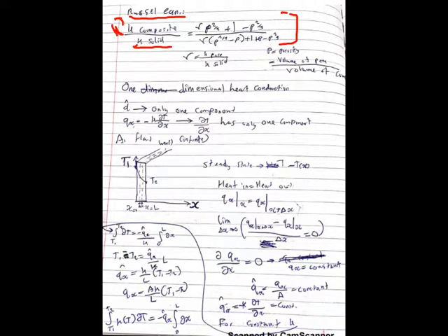We have this squiggly, which I don't know what to call it, and that is basically a ratio of the thermal conductivity of the pore, i.e., what is the pore? That is, in our example, the pocket of air or liquid in the wood over the thermal conductivity of our 100% pure solid. Now, this is simply a ratio, and we need it for the sake of the equation.